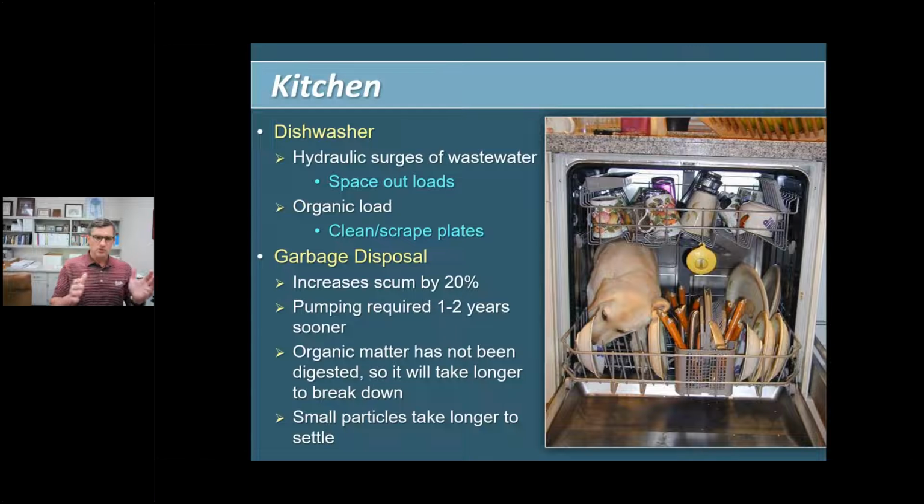In a perfect world, you would have a fairly consistent flow and a fairly consistent loading into your septic tank from a treatment standpoint. But we all realize that's not necessarily true, because with my household, we probably wash dishes every day, but we wash clothes on the weekends. We have a lot of loading of that on the weekend.